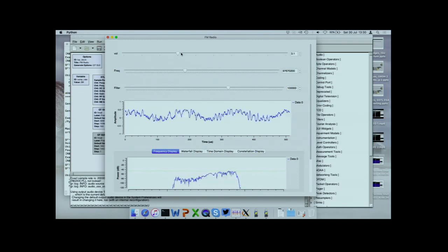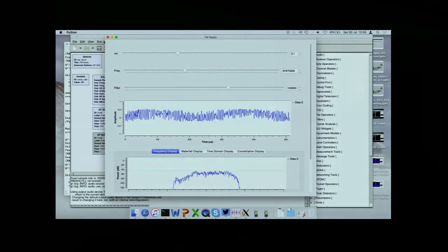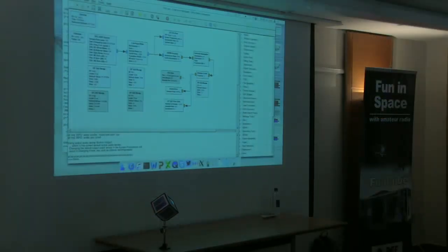You can see what I've been actually outputting is essentially drag and drops of all of these blocks together, and I've just happened to center it on an actual signal here. Now, if I didn't want to look at the audio coming out, I can just disable blocks. I can go in and go, yeah, I don't need to see that anymore, that looks good, let's just get rid of that. And so you've got these guys here, a sink, and I've got a time sink on there.